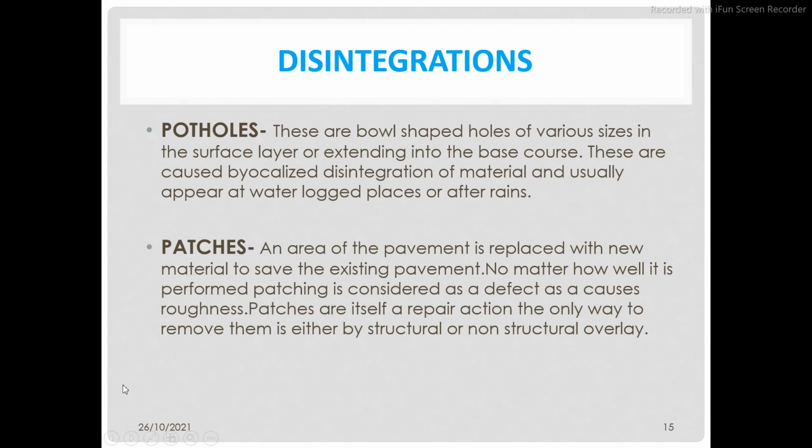Second one is patches. The area of the pavement is replaced with new material to save the existing pavement. No matter how well it is performed, patching is considered a defect as it causes roughness. Patches are themselves a repair action, but the only way to remove them is either by structural or non-structural overlay.